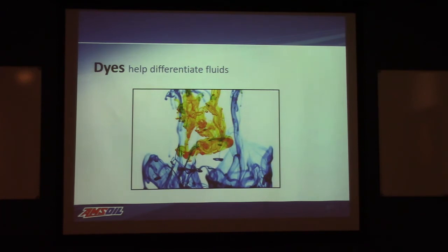Another thing that we may put in the oil, dyes. Why do we put dyes in there? Dyes don't perform any type of, or provide any type of, performance improvements or benefits. They're there for identification only. Automatic transmission fluids for cars tend to use a red dye, where the engine oils will tend to use usually an amber color dye. Reason for it? Quick identification.